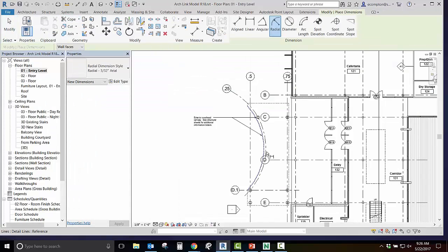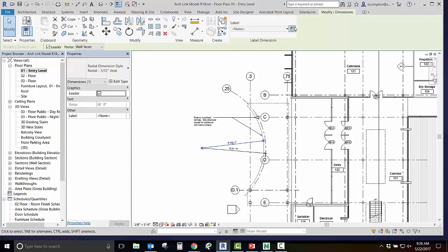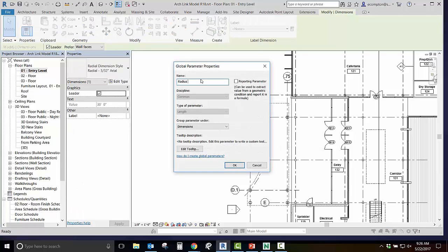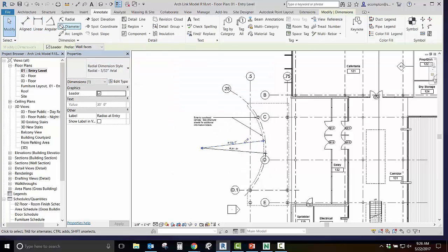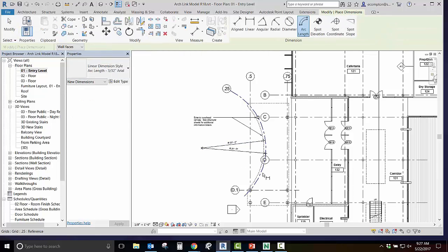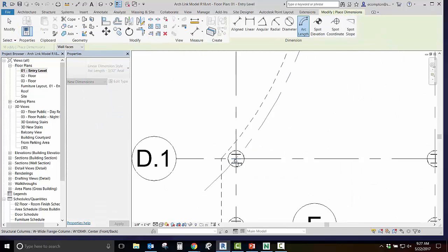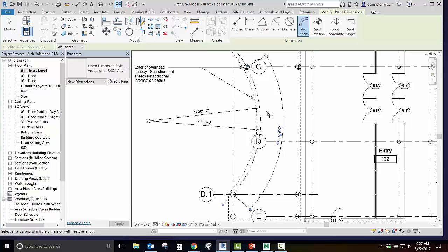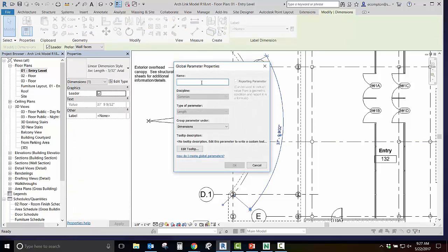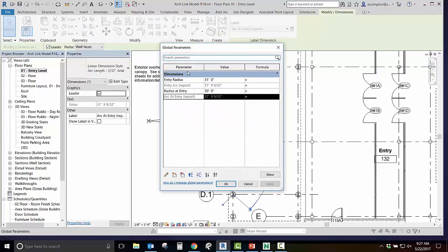2018 also makes available the addition of radius and arc length dimensions to global parameters. This expands the usefulness and control afforded by global parameters. With global parameters, the parametric qualities of the family editor are made available directly in projects. This allows named constraints to be applied to distances and parameters. We can define critical hold dimensions and flex labeled dimensions.